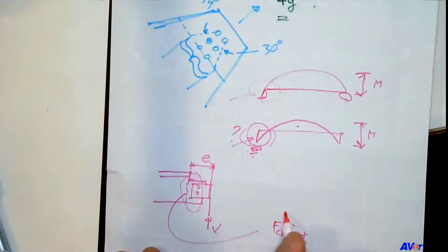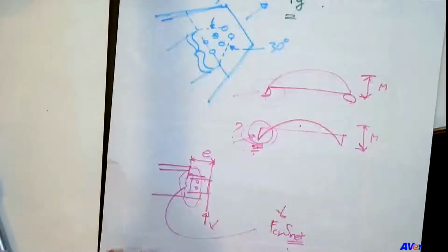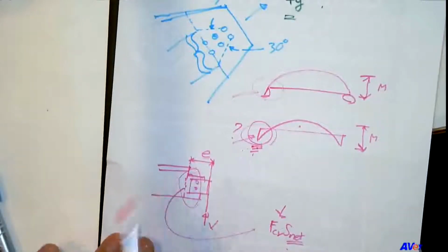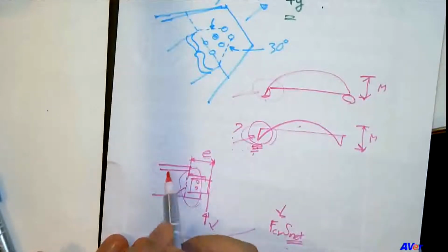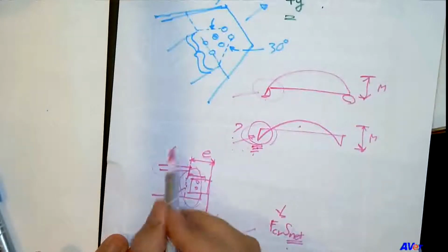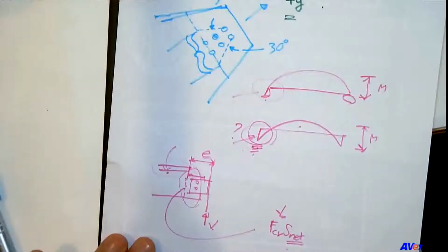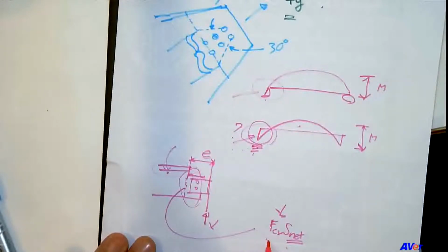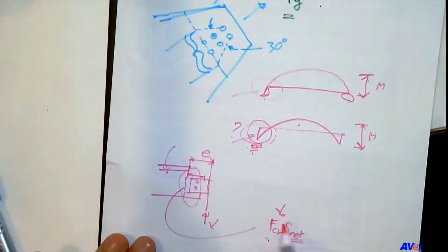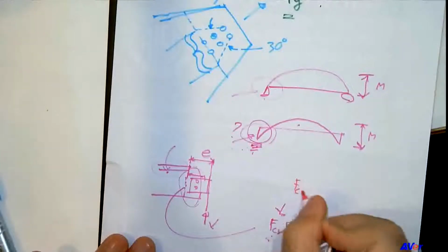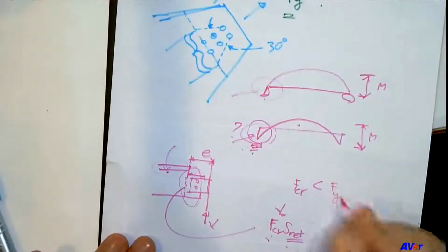And we use F critical, ladies and gentlemen, not Fy, because right here is compression, right? We have a simple beam. So on top is compression. So that means the compression coming from the fact that this is a simple beam carrying positive moment may cause buckling to occur here. So we need to check the critical buckling stress. But again, many times you will have a large number for this. So your F critical should not go beyond Fy, okay?